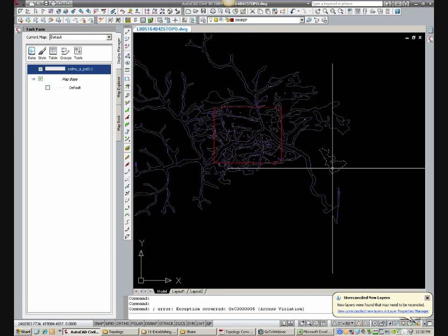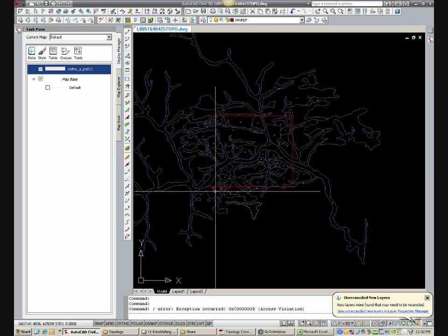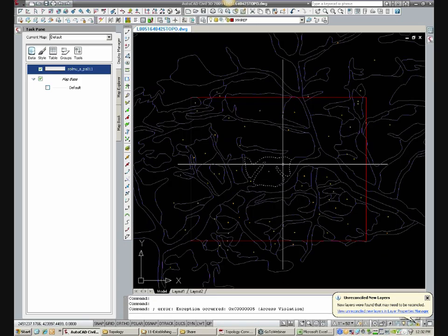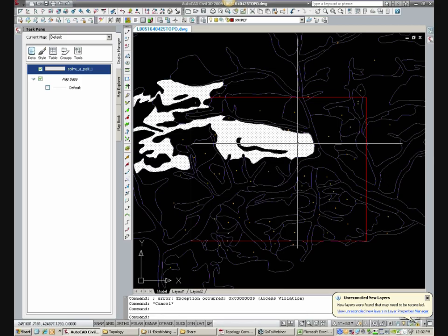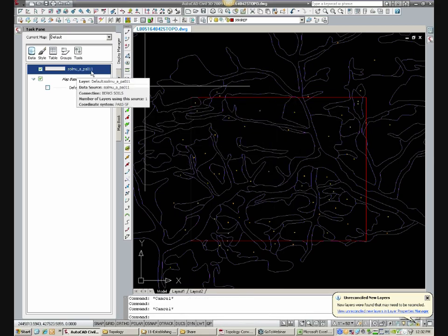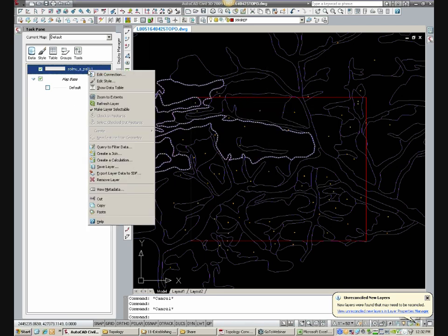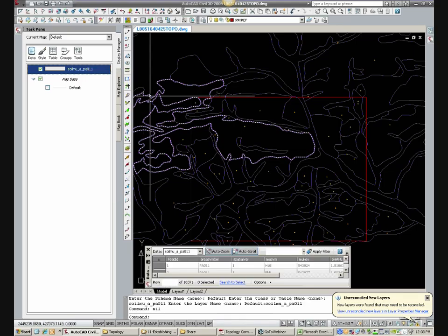And now you can't see that soils map anymore, right? But what's very unique here is that if I click in any given area, it still highlights the whole boundary. Really, when I'm clicking that, I'm clicking this object. So how does that help me? Well, I can right-click on this now and hit Show Data Table.